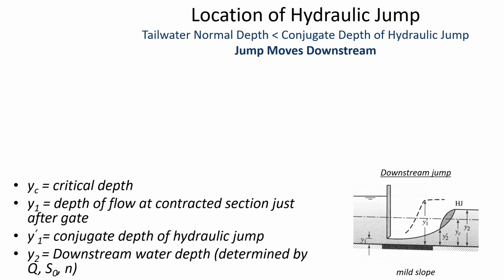What you'll see most of the time where they're forcing a hydraulic jump to set up someplace is that you'd want it to set up away from the gate or away from the spillway. And the way that we can understand this is that there's a period of gradually varied flow. So the water is just increasing a little bit, and then eventually it gets to some depth that is the match of the normal depth for the channel.